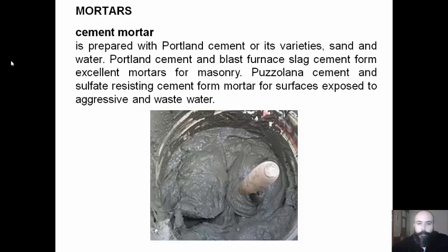Cement mortar is prepared with Portland cement or its varieties, sand, and water. Portland cement and blast furnace slag cement form excellent mortars for masonry. Pozzolana cement and sulfate-resisting cement form mortar for surfaces exposed to aggressive water and wastewater.